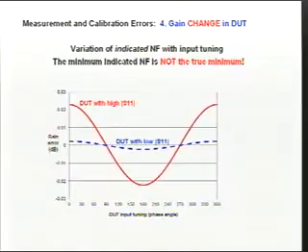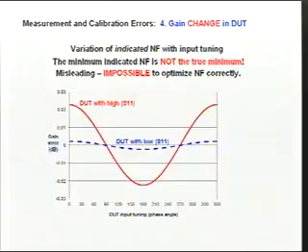And this, I think, is part of the reason why some preamps at different measurement places end up giving really quite similar results, because they are the same noise source, the same model of noise source, with the same physical internal dimensions. So the phase angle is the same, and if you're there, then you can go somewhere else with a different noise source, and quite possibly you will still be there, indicating a low noise figure.